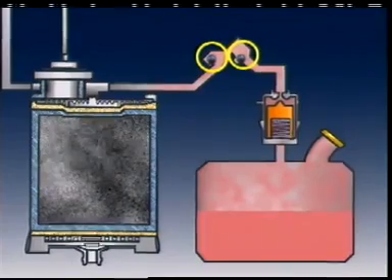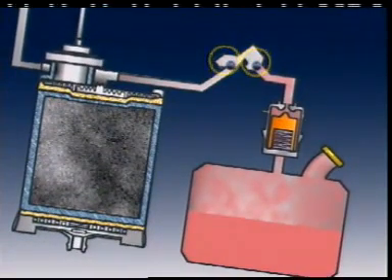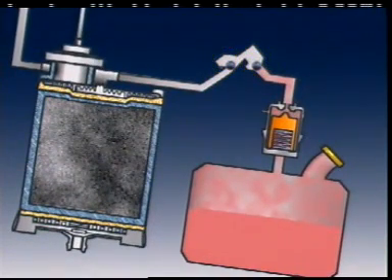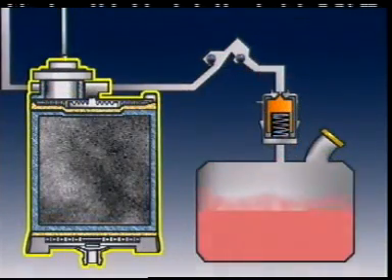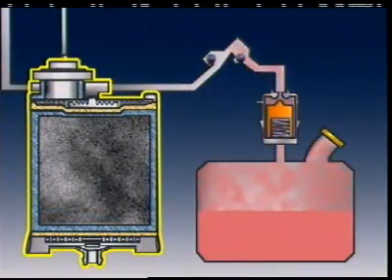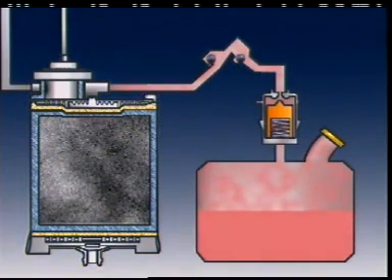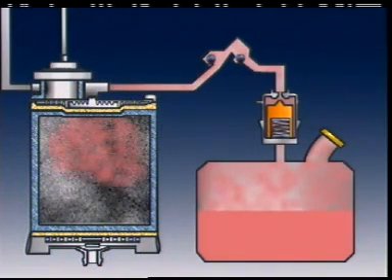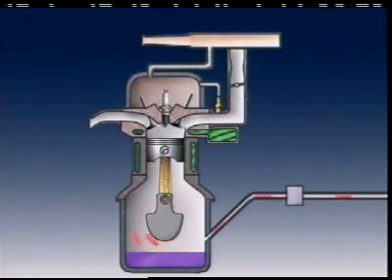This vapor line can incorporate check valves. If the vehicle is tilted too far from the horizontal, they stop liquid fuel entering the storage volume. A storage device is used to store the fuel vapors. The fuel tank breathes through this storage device. Some vehicles use the engine crankcase.